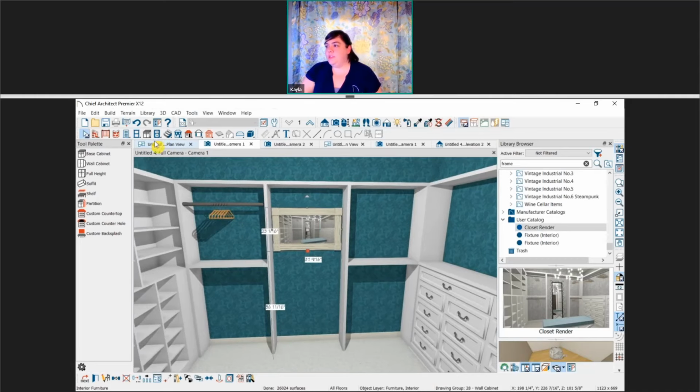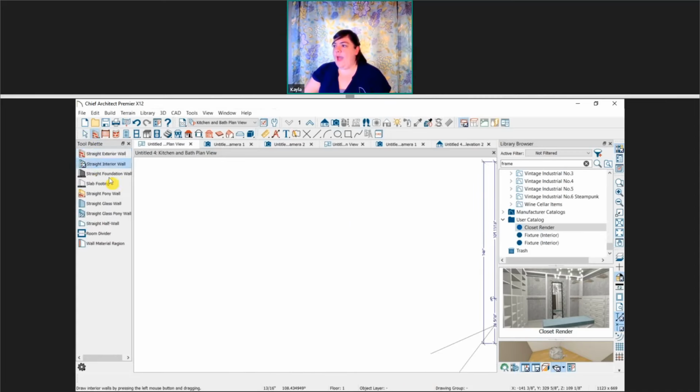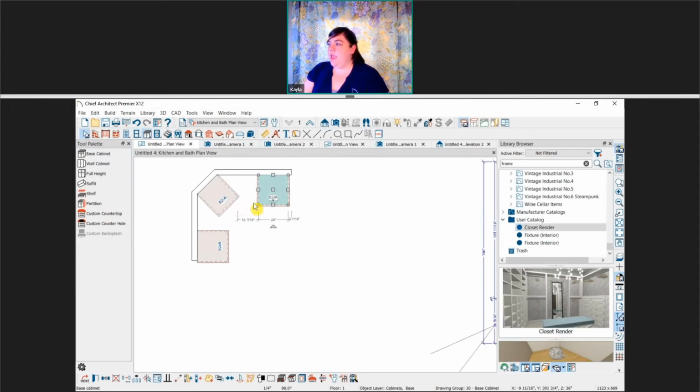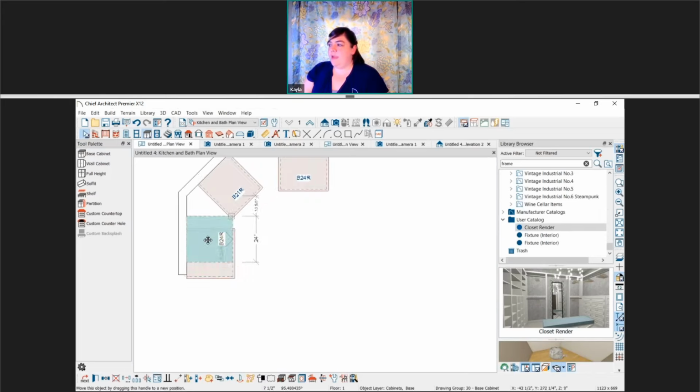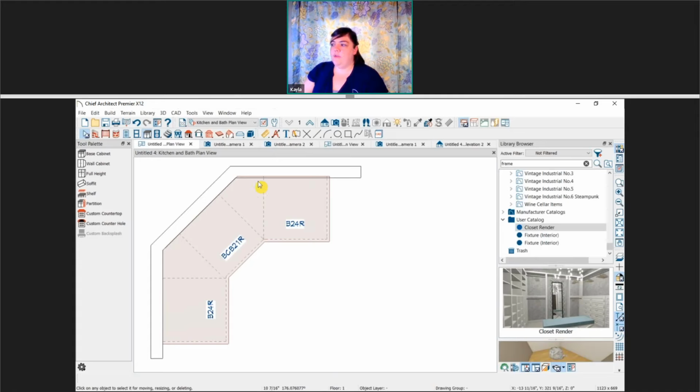Okay, you were breaking up a little bit there, but it sounded like you were talking about angled walls. For the most part, we're going to deal with this mostly with our countertops, if I understand your question correctly. So I'm going to move over to another area. If we have a wall and maybe a 45-degree angle, what I typically do is start by placing the angle, and then I'll place one cabinet in either direction. Depending upon how it's going to meet up, let's do a little bit more room here. I will just move it until it bumps right up against that corner. It'll try to snap right to that corner, and then it'll fill in those blank areas for the countertop.